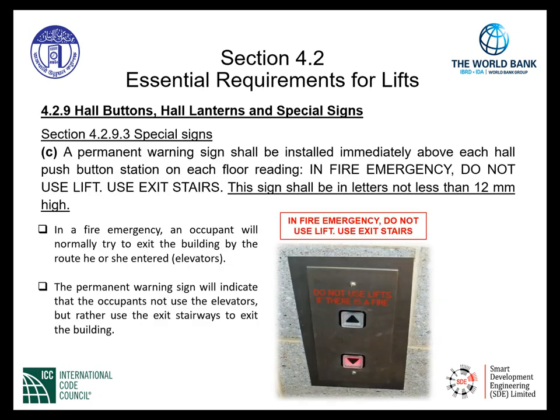Special signage, in section 4.2.9.3, item C. A permanent warning sign shall be installed immediately above each hall push-button station on each floor, reading, "In fire emergency, do not use lift. Use exit stairs." This sign shall be in letters not less than 12 millimeters in height.